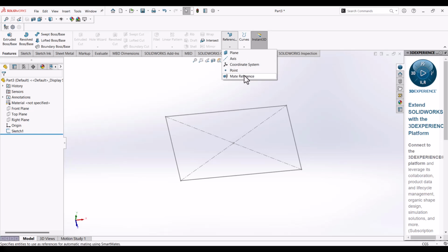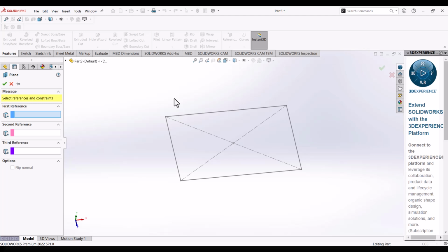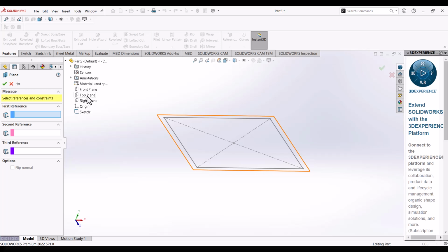Each of these options has a role. Once I select plane, plane gives you the opportunity to select multiple surfaces to create multiple layers of sheets. I click on my design tree, and it drops down. The first plane that I drew on was the top plane. So it asks what reference you want to make the plane to, just like you have a sheet of paper, then you bring another sheet of paper.